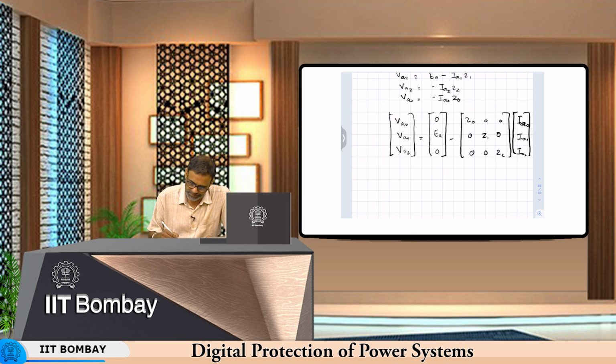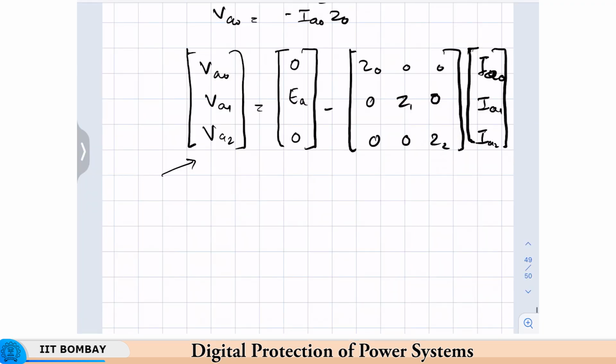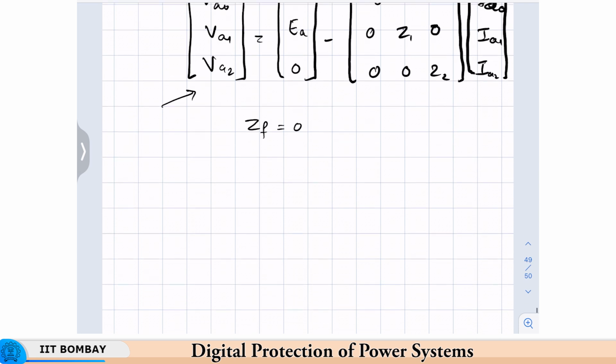So, this is the basic equation which we will use for developing equations for all our faults. Now, we will take the case of solid faults. We are not considering any fault impedance, which means that ZF is equal to 0.